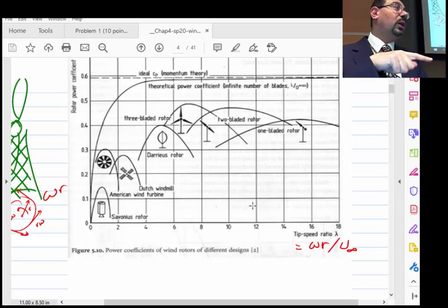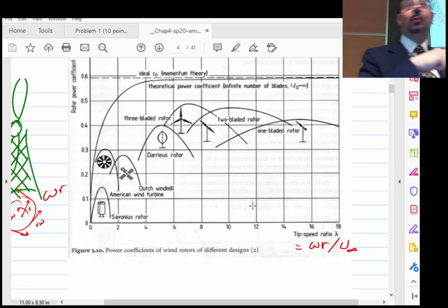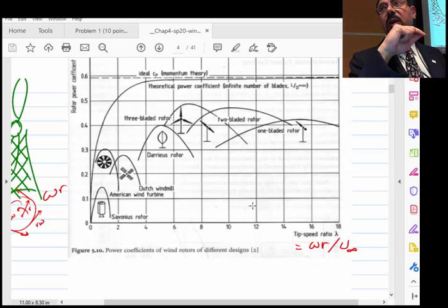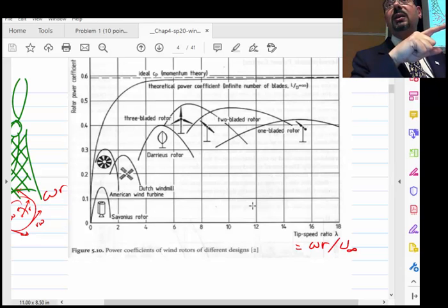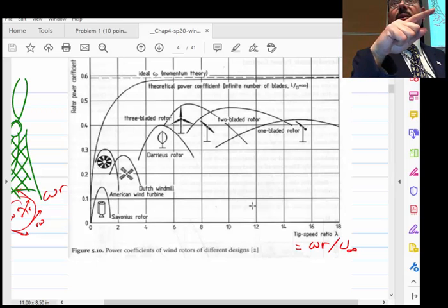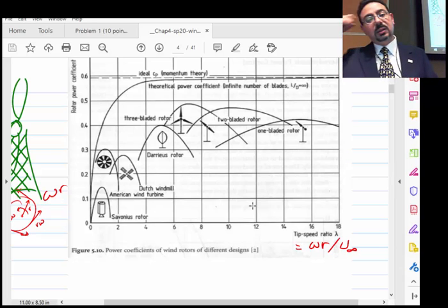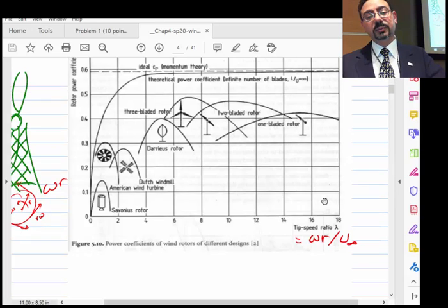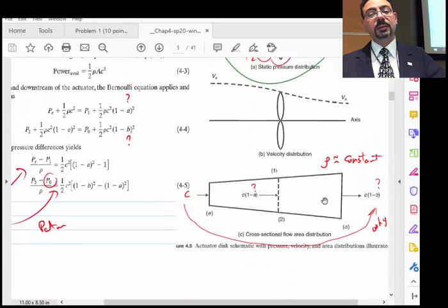And so if you are lucky and you find a paper that says we invented a rotor that ends up harvesting higher than the Betz limit, then check the analysis and see how they managed it. How did they manage to make the flow leave even with velocity lower than the maximum allowed, lower than the lowest allowed? Alright?